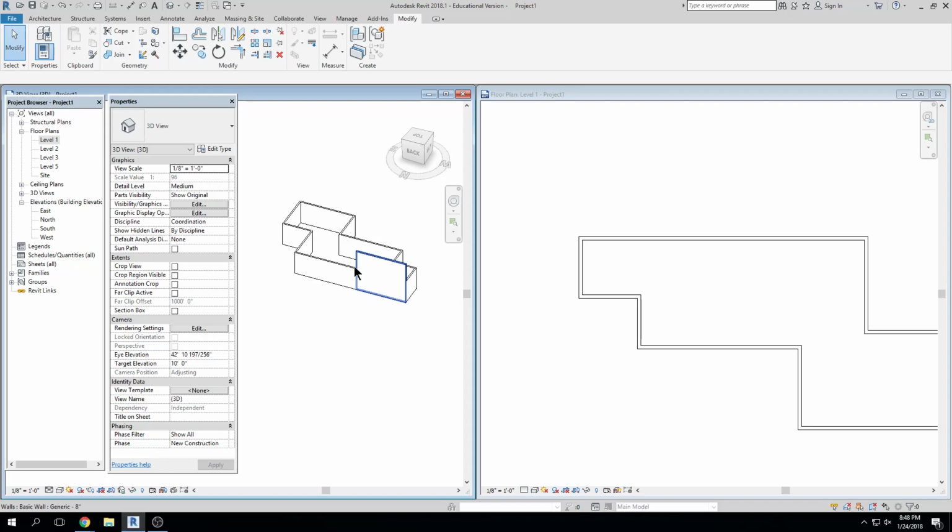Our interior walls will start at an interior point, likely the top of that slab right there. See how we're starting to get a few different levels here? And they'll go all the way up to probably the underside of the structure. And we'll have a few more datums that come up here. Does that somewhat make sense? So exterior walls span from floor to floor, however tall they need to be. Interior walls go from floor to bottom of structure, generally.